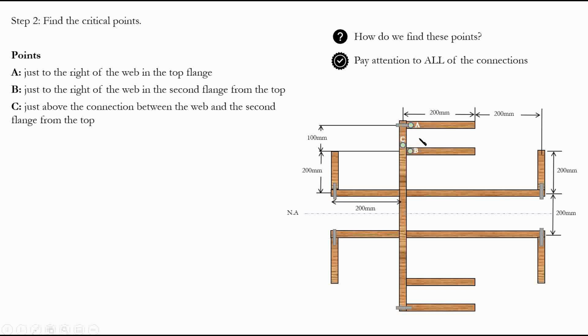And why do we do that? You'll see when we are drawing, all of this will become very clear when we are drawing the shear stress distribution in the web and the flange, right? Especially in the web. So why we are finding the C, that's the importance, right? Because you have a Q value here and a contribution from this point.